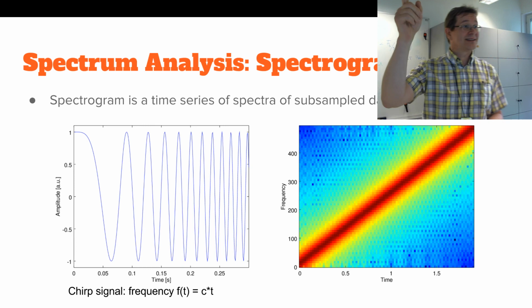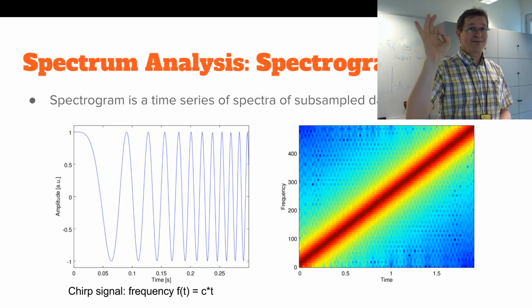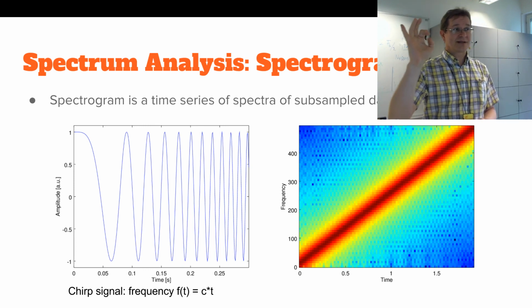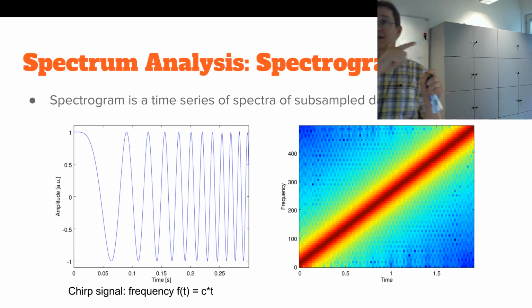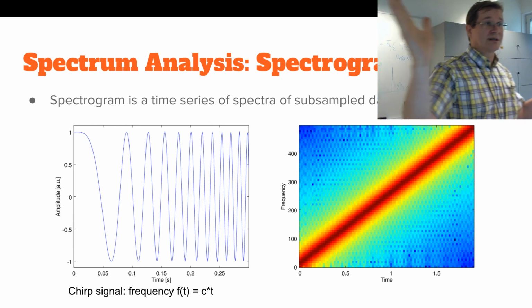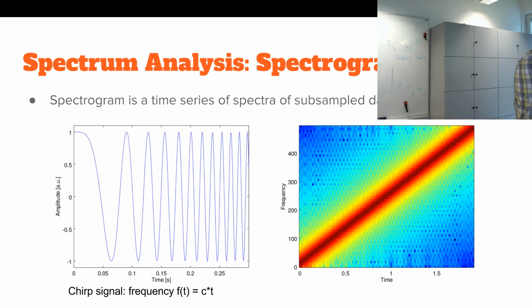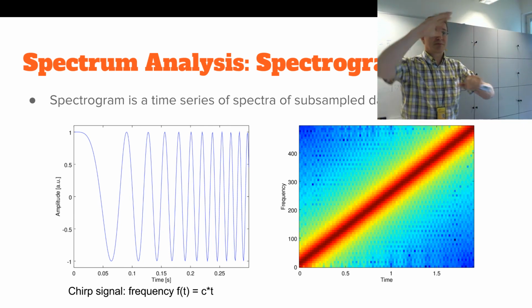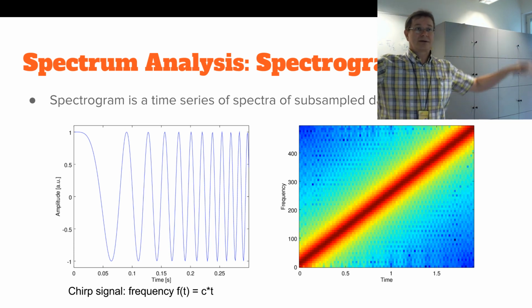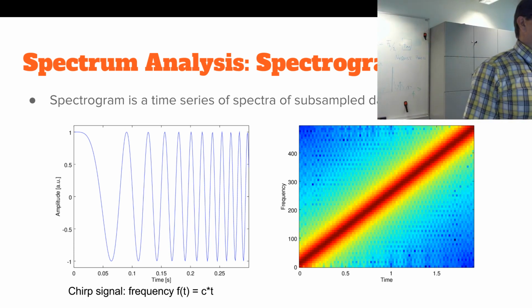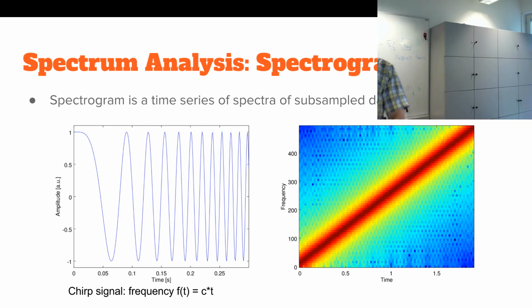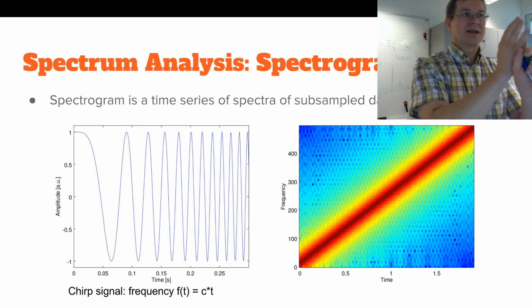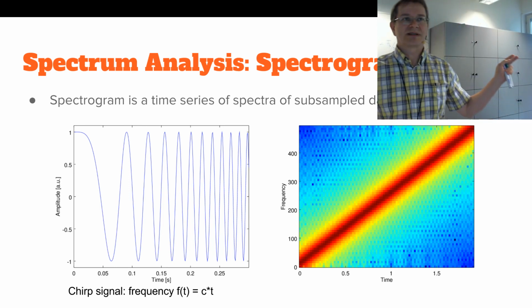It is an excellent test vector for any acoustic system, since it's basically a chirp that starts at some frequency and ends at some frequency. You can just run the chirp and immediately get from the power spectrum the amplitude response of the system. So you're measuring the system at individual frequencies, but all of those frequencies are in one single sample of the test vector.